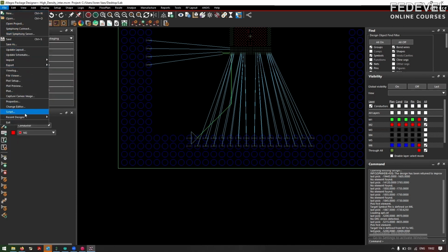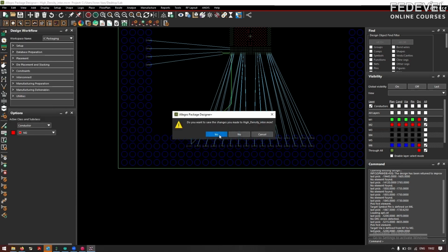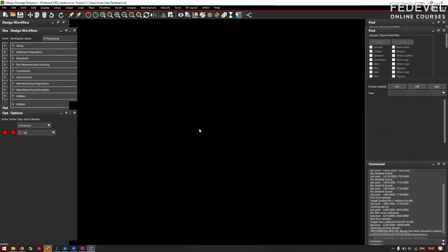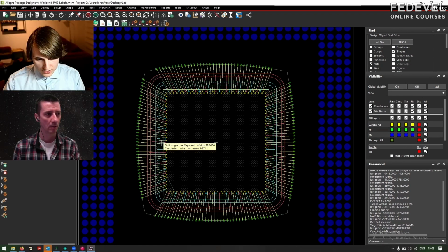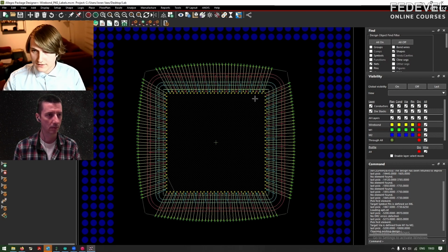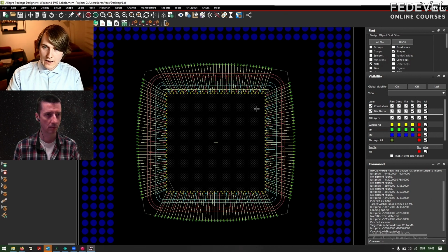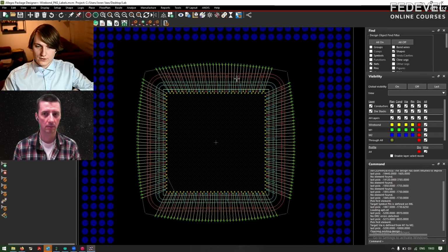So you go, for example, here, this is a BGA with bond wires. In the center here, this is the chip. And then around this, they've placed the pads on the BGA substrate. And these blue, red, and yellow lines are the bond wires. So the packaging house knows, I have to draw a wire from this pad and pull it to that pad, and so on. They make this for you, and then the chip is connected.